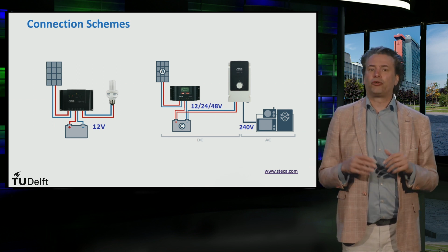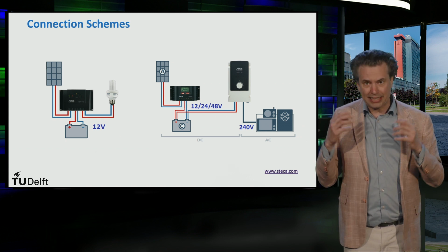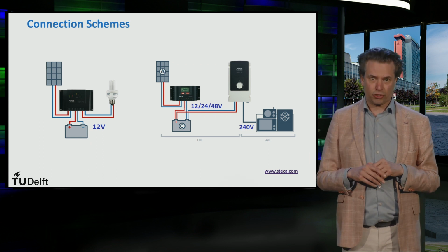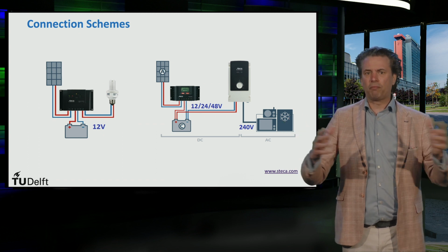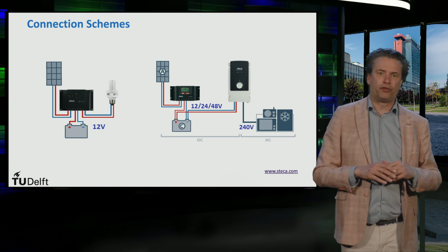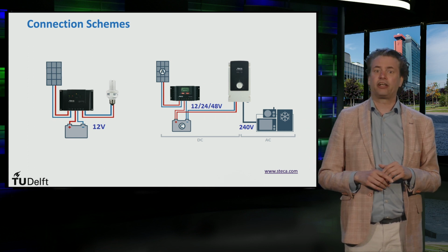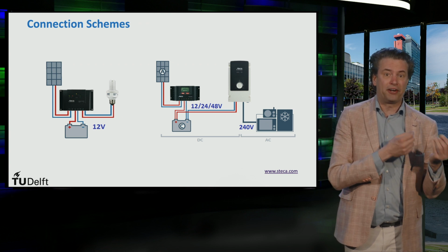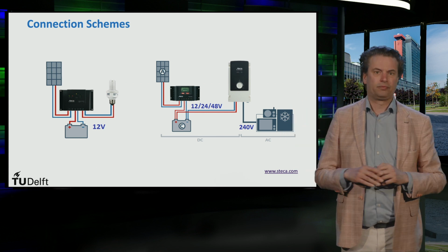This is because charge controllers may not be able to handle the high currents delivered by the batteries to the inverter. This means that the battery discharge protection that is generally available inside a charge controller is now available inside the inverter. This is sometimes accomplished by an automatic shut-off below a certain voltage, since the voltage drops with the state of charge. Thus, in this particular scenario, the charge controller will prevent only the overcharging of the battery, while the battery discharge protection is carried out by the inverter.